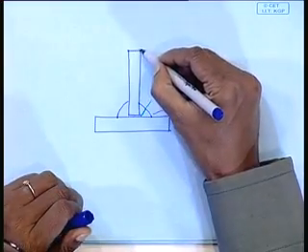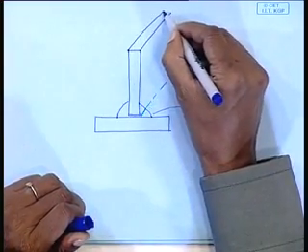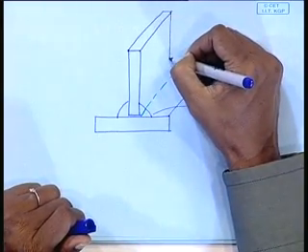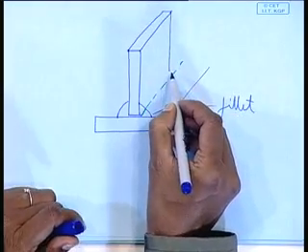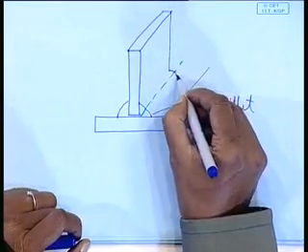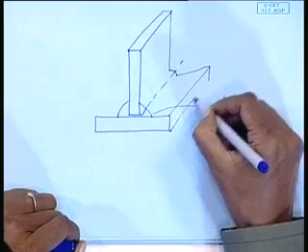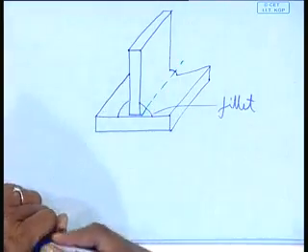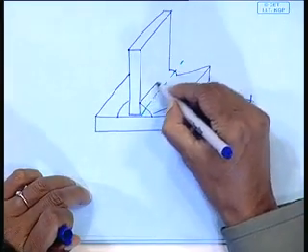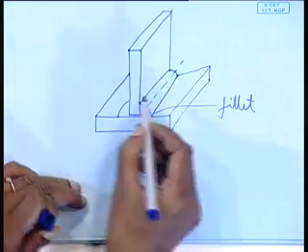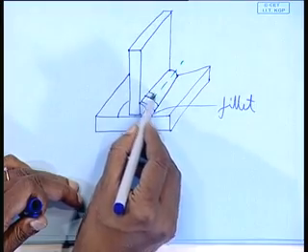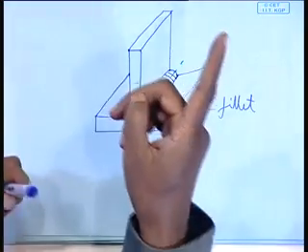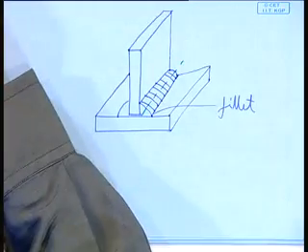That means, while the metal is still hot, it is cracking, and it is also referred to as solidification cracking. It means the metal is getting solidified and the cracking is taking place. This is your deposition. This is the fillet deposition, right, and along the green line you find a crack developed all along. That is what is referred to as solidification cracking.